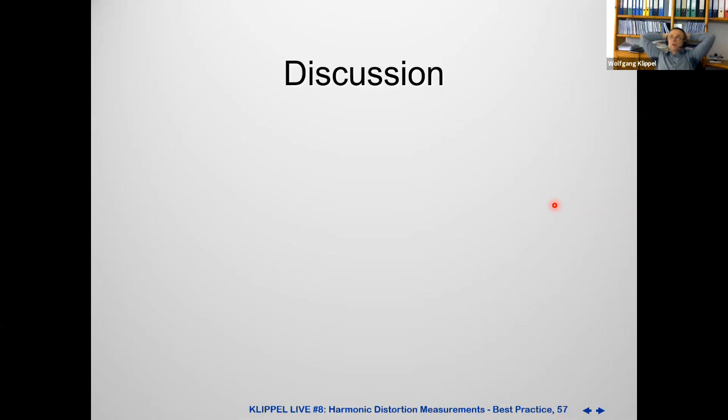The mechanical Q, the high Q values are dangerous, because it's ringing very long, and to get steady state condition you have to wait for a while, and you get the high Q values usually from the mechanical Q. So if you are speaking only about the fundamental resonance, this is not a big deal. Why? Because usually the electrical Q is dominating, providing enough damping also for the mechanical things.